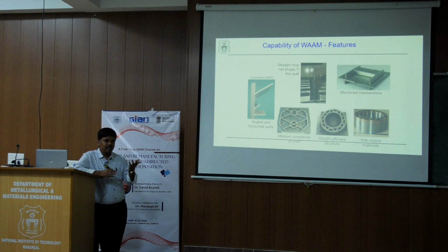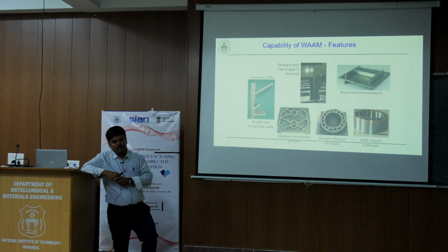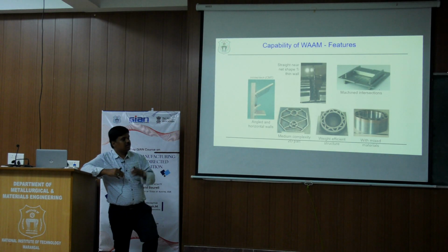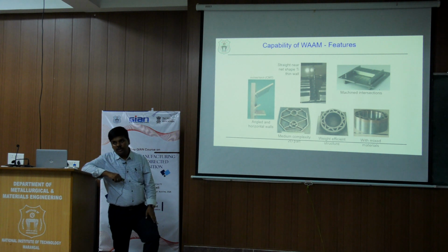In PBF, making bimetallic components is highly challenging. It's very difficult because we have to mix the powders, or we end up with scrap of the powder particles. But in DED, without losing the powder materials, we can feed n number of materials when we have a larger number of feedstock hoppers. With the same machine, we can provide bimetallic or even functionally graded materials.